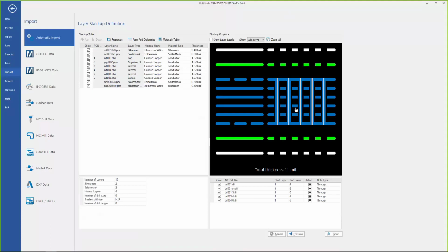As you can see here, we try to do that automatically. If you have to move them around, you can move them around. But when you're working with NC and Gerber, there's really nothing that tells us, specifically, what the layers are. So we do make some assumptions, and we may get them wrong. But once you do put these in the correct order, working with the partial vias is as simple now as a drag of your drills to show which layers those particular drills go through.